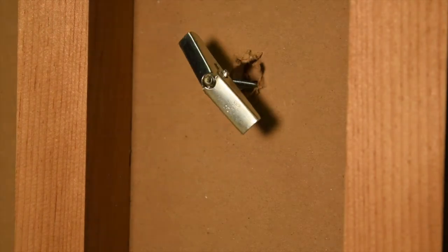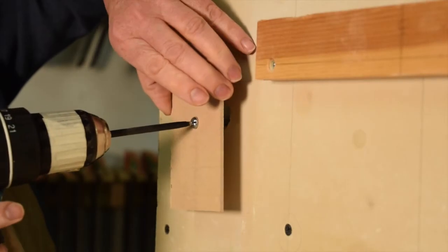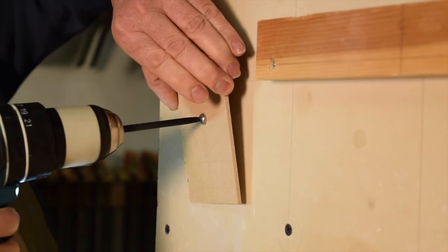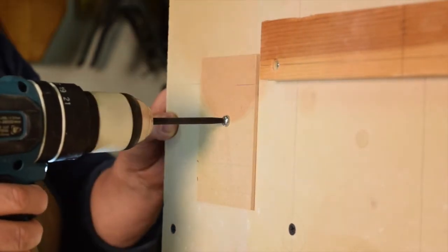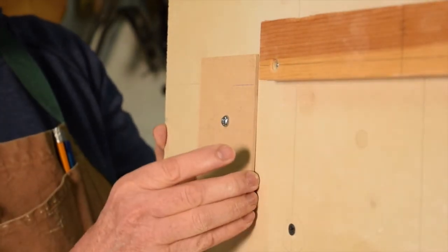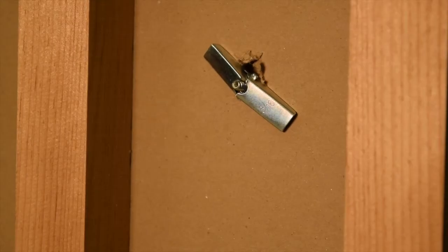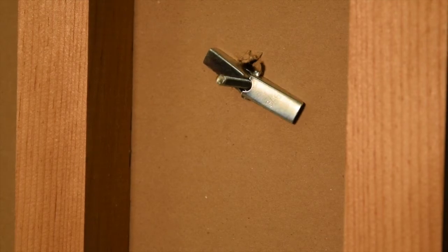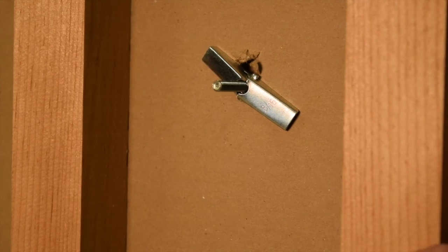So the toggle clip just flips open, and I've pulled it back so that it's tight to the back of the drywall. You can see I've had to pull the piece I'm trying to attach to the wall back as well. If I don't do that, the toggle clip just spins around. So I need to have it tight up against the back of the drywall as I'm driving the bolt through to get a nice snug fit. And we'll just take a look at what that looks like from the back. You can see I've pulled it back and the toggle clip stays in its position and the bolt comes through.